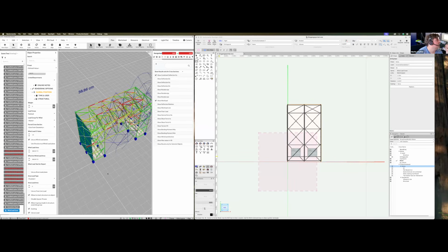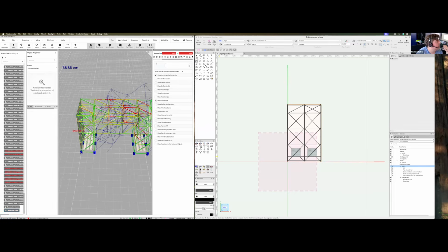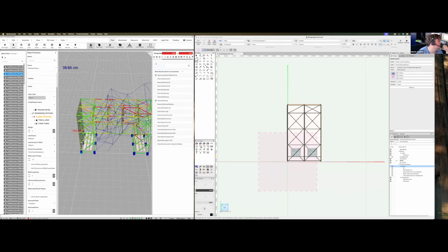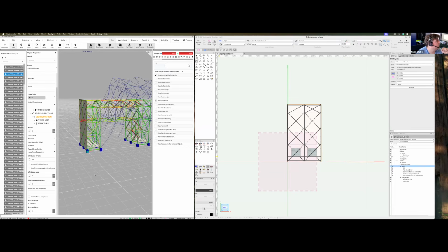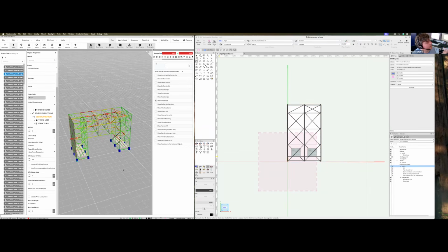We need the support in here to calculate properly. The next thing would be calculate ballast, which would write the ballast into these things and calculate how much you need in order for this not to tip over. That's basically how the scaffolding stuff works.